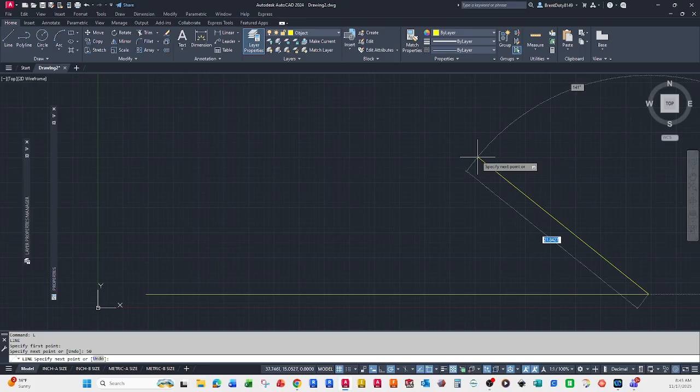But what happens is, if I continue doing this, then I may not be able to zoom in and out very well, and because it's so far out of the limits, normally what happens is you're not zoomed out far enough to where it zips on out of your screen. Okay, I'll just be honest with you, normally that's the way it works. And you know, students are like, what the heck? Well, at first it wasn't a big deal of, hey, you need to adjust your limits, because you do your limits and then you zoom all or zoom extents so that you can see everything.